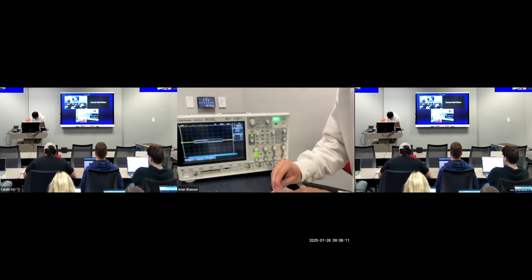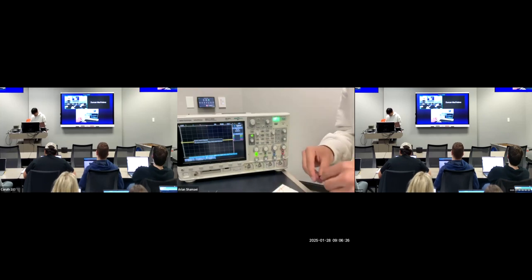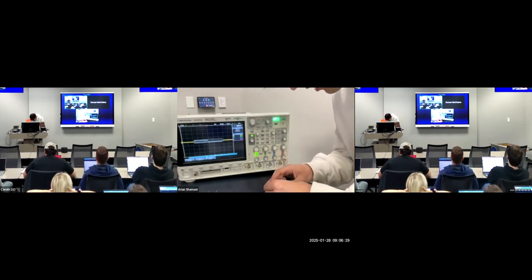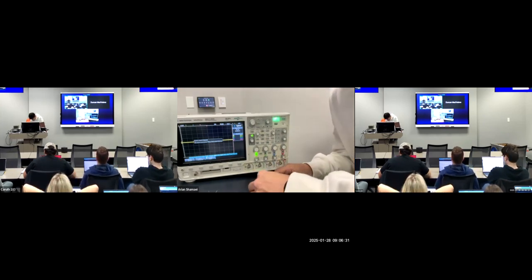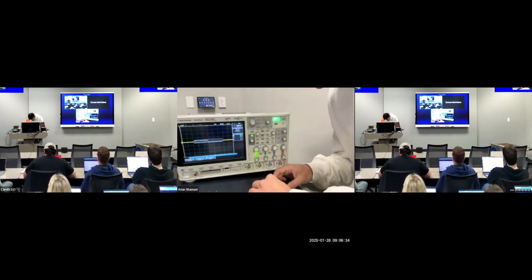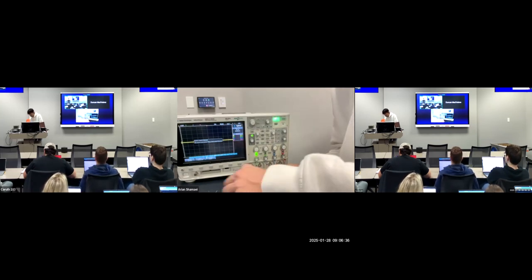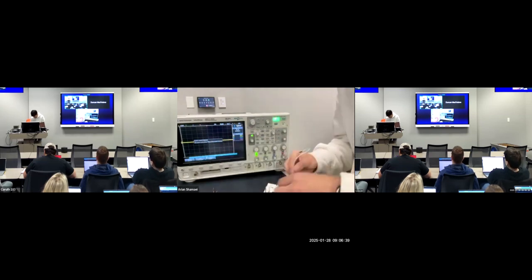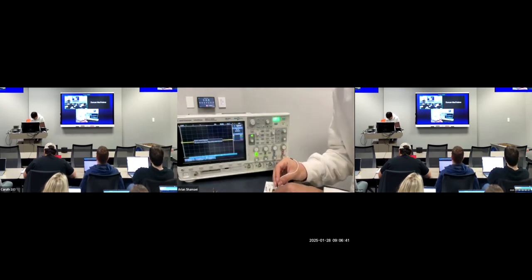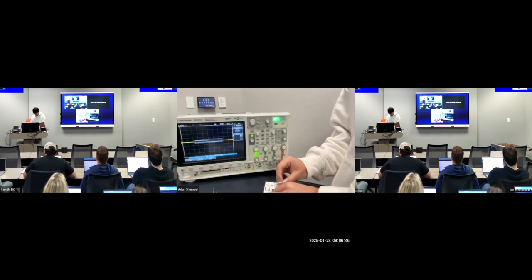I used LM741s in Circuit 1 lab quite some time, so I'm used to the pinout and don't have to reference the data sheet. Usually you reference the data sheet for the pinouts. I have a 5K resistor for R2 and a 1K resistor for R1. I'm going to connect the power to the power rails. I'm not going to bias it, so I'll just keep it to V plus. V minus I'm going to put to ground. Sorry for my wiring, this is really messy.